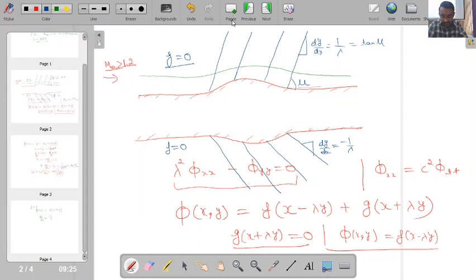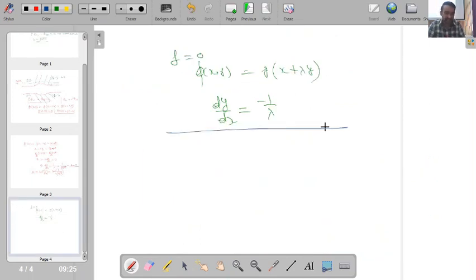So up to this point, is it clear? So now our interest is to calculate the value of Vx dash, because what is the definition of Cp? From linearized theory, our pressure coefficient is minus 2 Vx dash by V infinity. So our interest is now to calculate the value of Vx dash. Okay, so Vx dash will be del phi by del x.